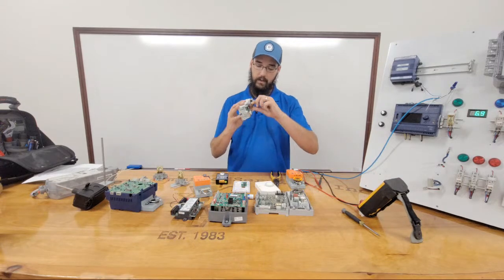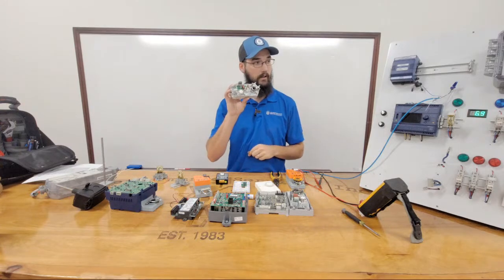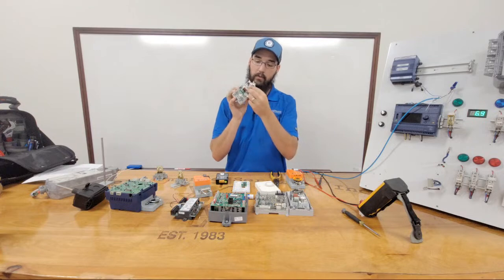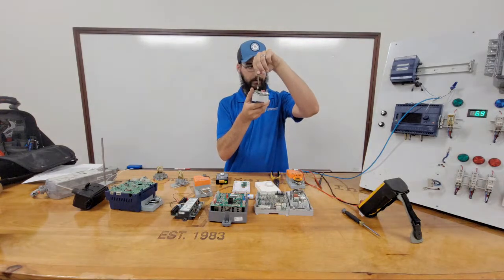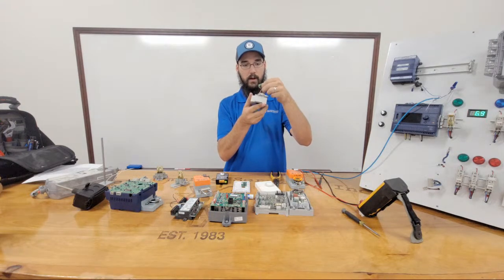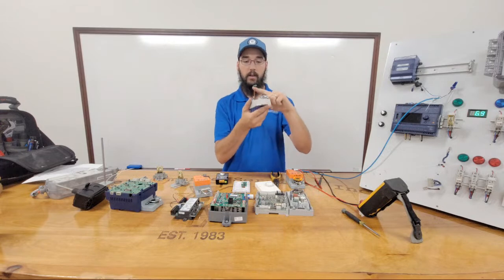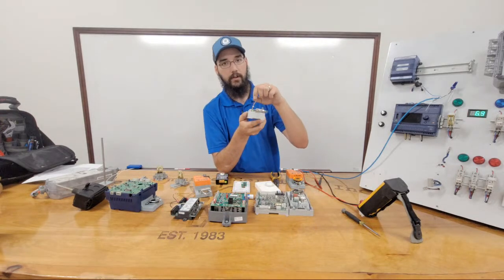Now, one thing really neat about Honeywell's is there's another little pin connector you can unplug. And what you're seeing there is now you have 4 little wires coming off of that to that green connector, and these 4 wires run straight to the motor. The reason there's 4 is because that's 2 different stators.